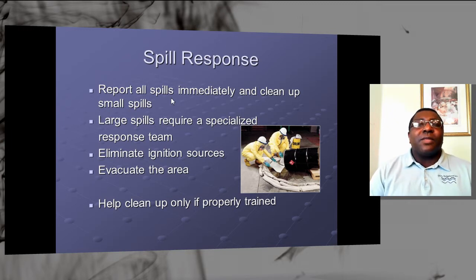You do that. But let's say you have a big drum like in this picture, and you have a spill of pesticide or a chemical solvent, then you may have to do a larger spill response. Any spillage you have to address immediately. The best thing to do if it's a large spill is barricade, just isolate the spill as best as you can.